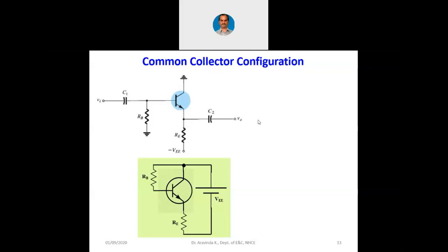Fine. Now I hope you have understood that the circuitry which I have shown at the bottom is the same as the circuitry which is at the top, except for the two capacitors. C1 is the blocking capacitor and C2 is the coupling capacitor, which are required for supplying AC input and taking AC output.